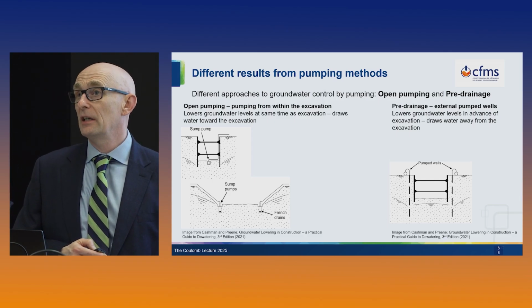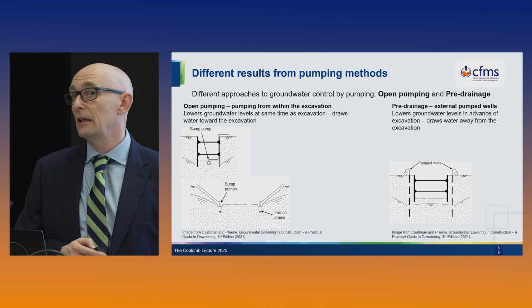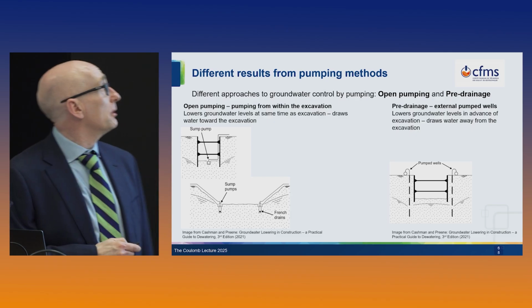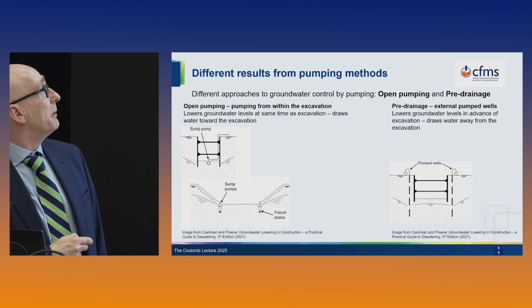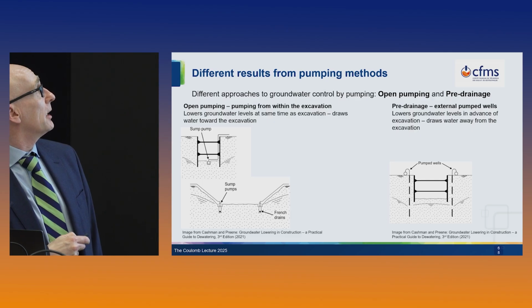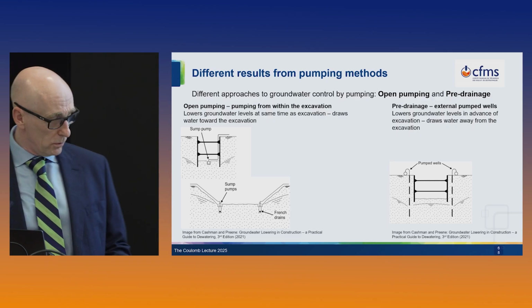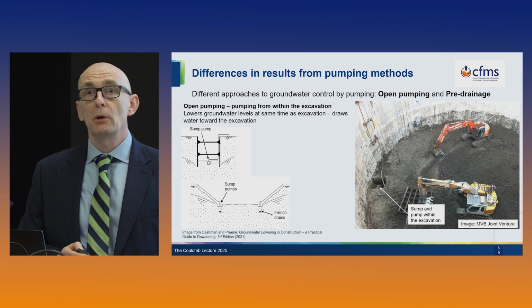And it means two things. It means we can't lower the groundwater level in advance of the excavation, and it means that, broadly speaking, we're drawing groundwater towards the excavation. So here we've got an excavation supported by sheet piles, and we have a sump that's pumping water. This is what it looks like in practice.